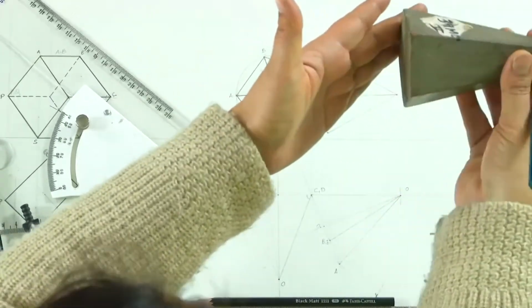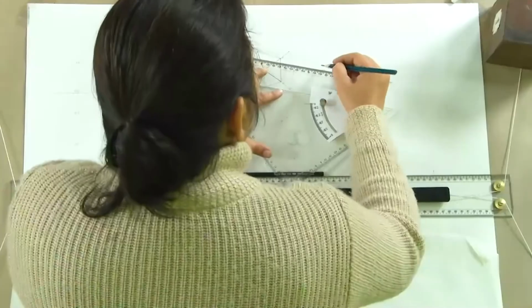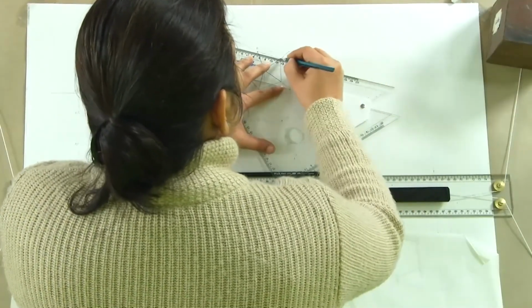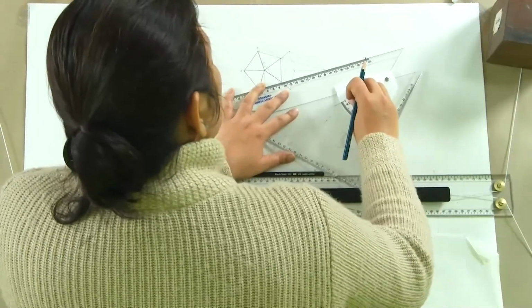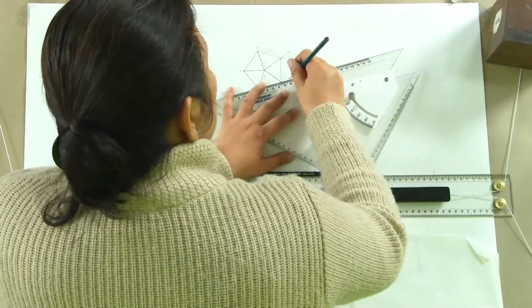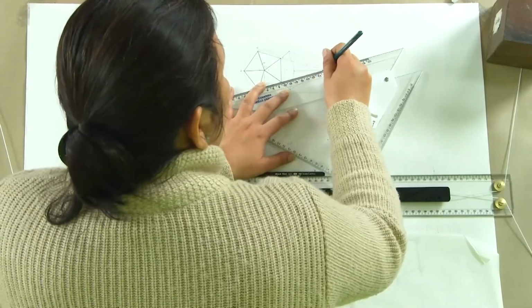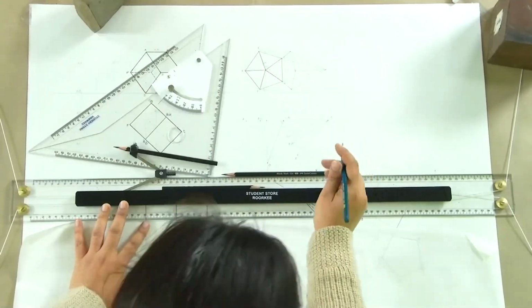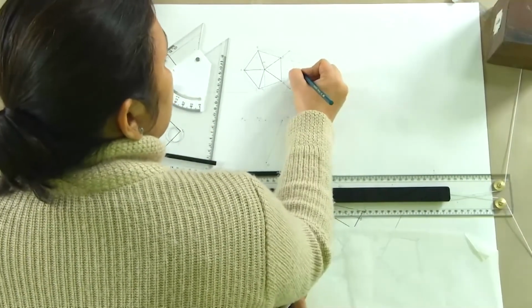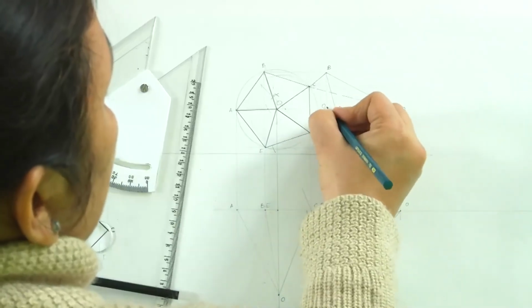So if this was rotated like this, what we see from the front is these two faces, while two faces go at the back, and one of the faces, if I draw the hidden line here, this face, which is a triangular face named OCD, is going to be the face which will actually be seen in its true dimensions, because it is absolutely parallel to the VP. So what we have here is A, B, C, D, E and O, and we also have an O1, which is the axis.